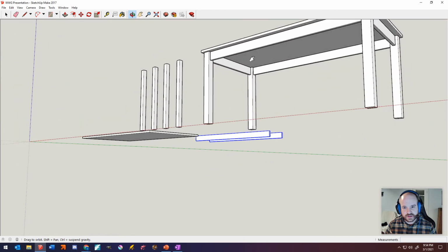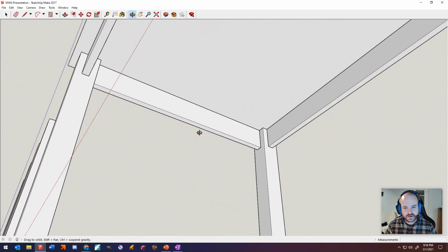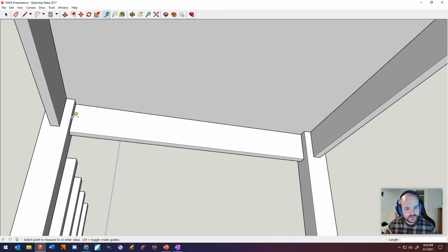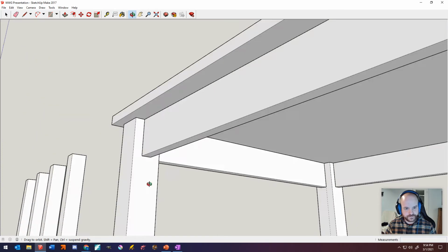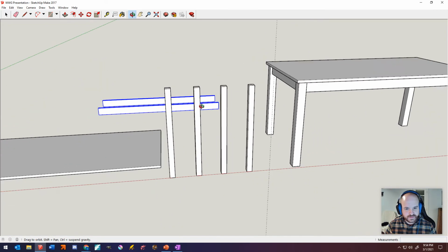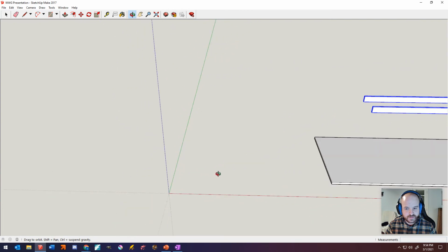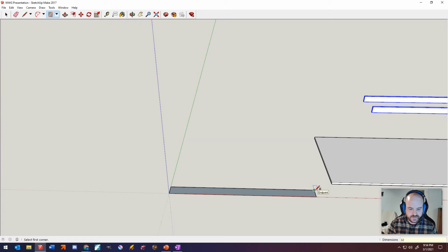I'm actually going to need to look at this to tell my actual dimensions. I hit T for tape measure, which is a great tool. T for tape. If you look at the bottom right hand corner, you see the length. So we've got 32 inches. Hitting O for orbit to navigate around. And I'm always going back to this origin point or this magic corner to make all my things. So we've got 32 inches, or R for rectangle, 32 comma, and I believe my apron is 1 inch wide. I'm a 1.